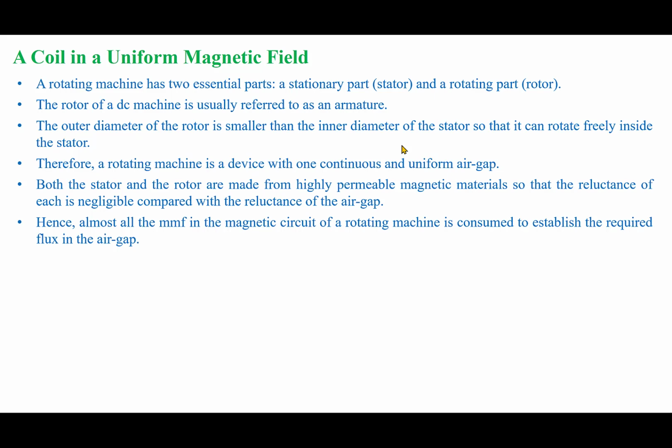Okay. So the MMF, that is actually it carries the magnetic circuit, which actually produces the flux and which is linking the armature circuit, will produce the EMF in the armature circuit, right? And when the permanent magnet is placed in the stator as a field, it produces a constant flux, right?